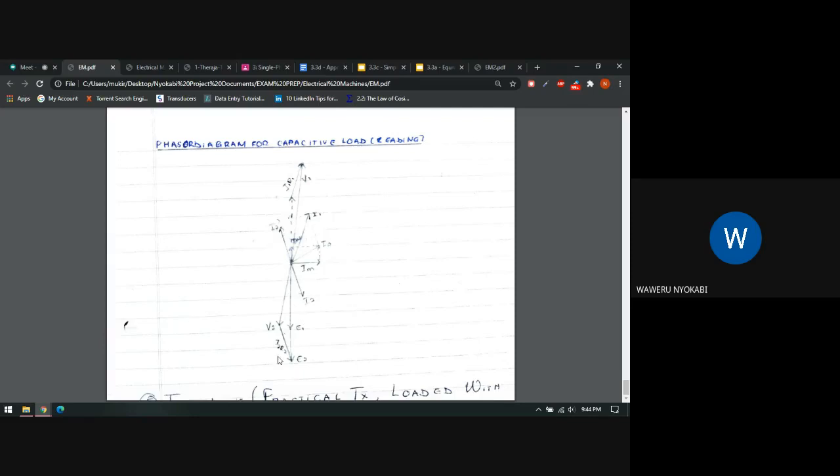This part is what fully explains why it's load dependent. You remember I1 has the components I0 and I2 prime. The reason why we have I2 prime is again because of that load.